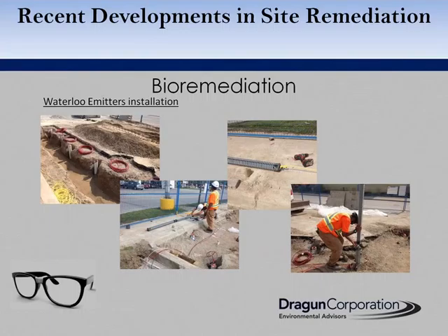Another thing is bioaugmentation is being carried out to supplement bioremediation, and this is accomplished through artificially inoculating the groundwater plume with biotics that are known to consume contaminants. There's also significant advancements in the area of trap and treat type bioremediations, and Matt Schroeder will discuss these shortly.